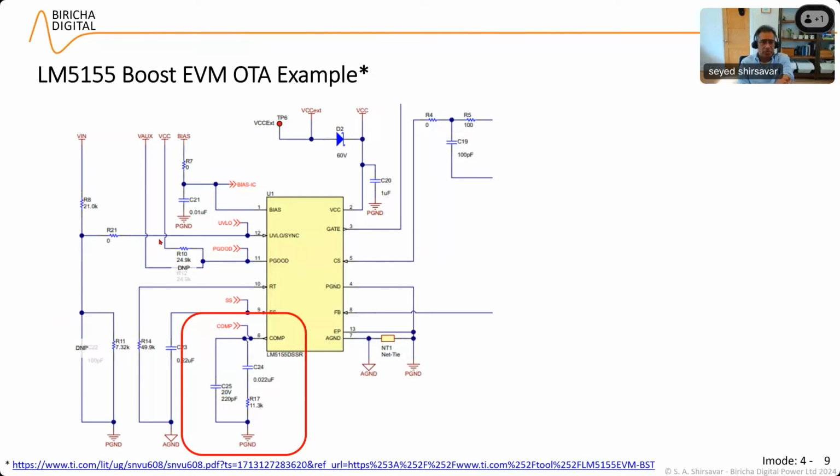Right. To give you a real life example, this is taken from a TI EVM, which is available for sale. You just type LM5155 boost EVM and you'll find it. And I've also given you the link down here. It's very, very easy to work out whether it's a normal amplifier or an OTA. All you do is look at the output of the op amp, and if the compensating components is tied to ground instead of being fed back to the input side of the amp, then it's transconductance.